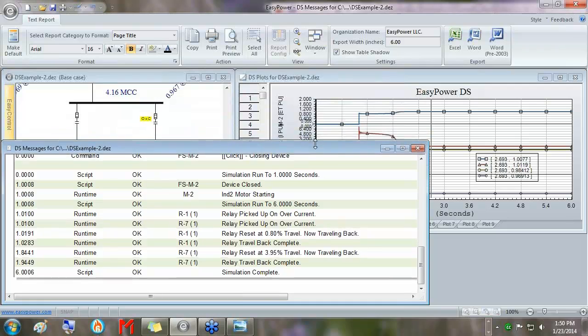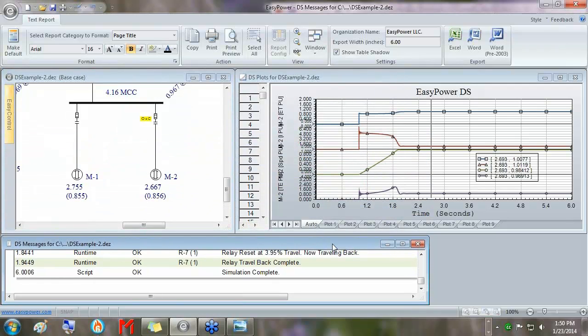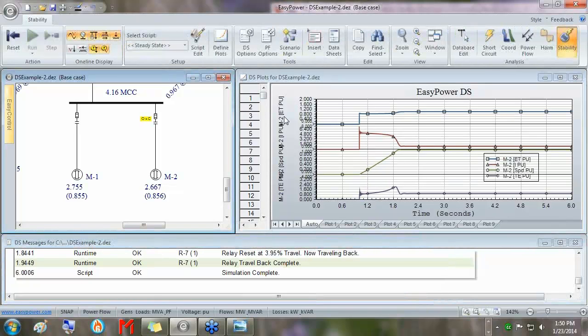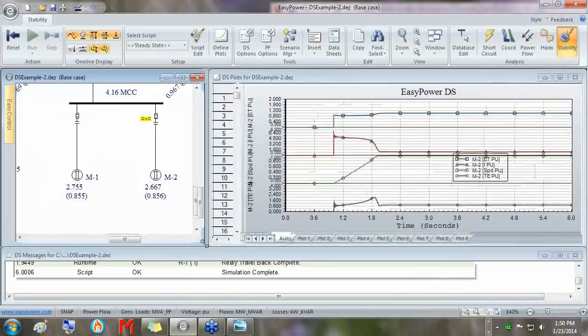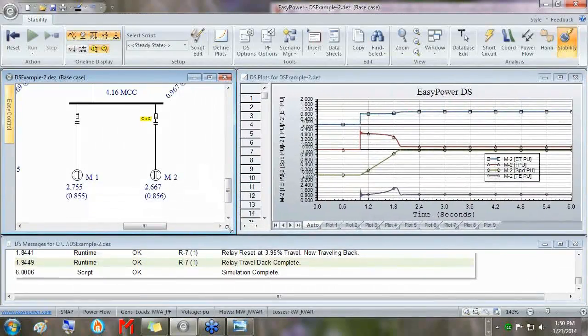So, valuable information here. Notice a nice trick. If you're in here, you have these 3 windows showing, you hit F8 and it puts them all back in order. Another trick: the bottom right-hand corner of the main one-line window, drag it and they follow. So you can quickly resize your windows.